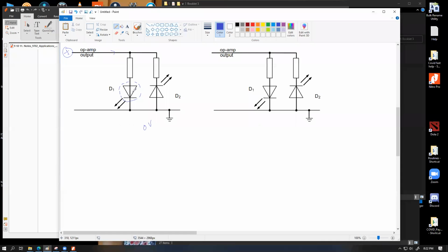It should be of some minimal power, because this LED will be glowing altogether from the current that will be drawn from the op amp. So whatever current this LED uses, the op amp should be capable of providing and handling that current continuously. So they will not be very bright LEDs, or very high powered LEDs, but they can essentially give you enough of a signal showing what the possible output of this device is. So they are good for close monitoring, or they can be placed on a single dashboard where you have multiple different LEDs showing you that this is okay, this is not okay.